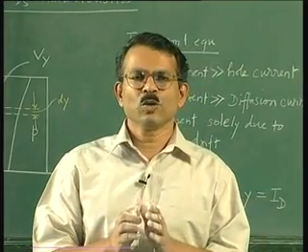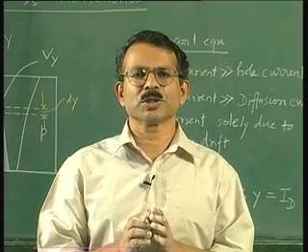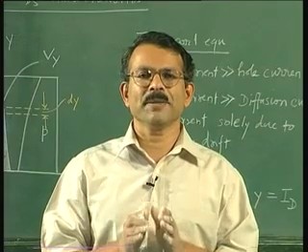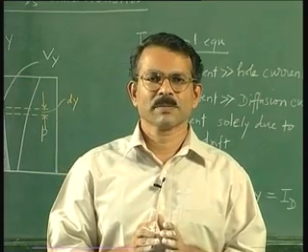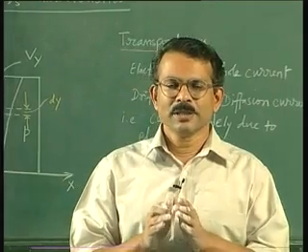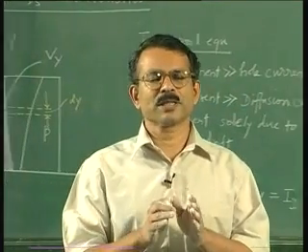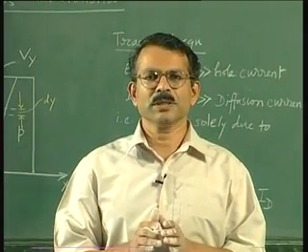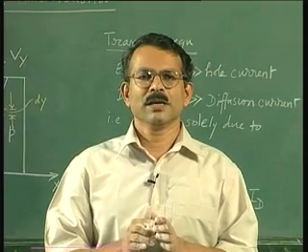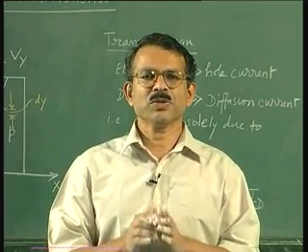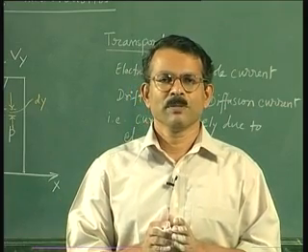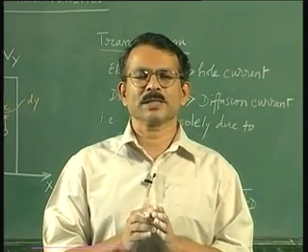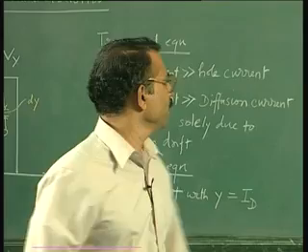That two-dimensional electric field or potential distribution has to be approximated to a one-dimensional distribution to simplify the analysis. This simplification is termed the gradual channel approximation in the context of Mosfets. So we will first write down what this approximation is and explain it.